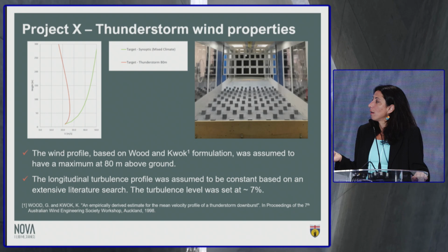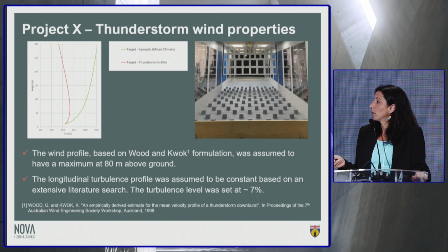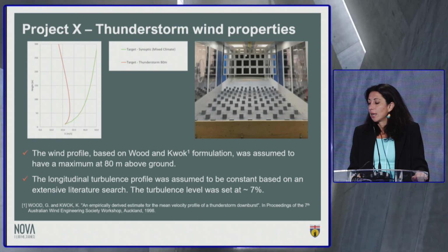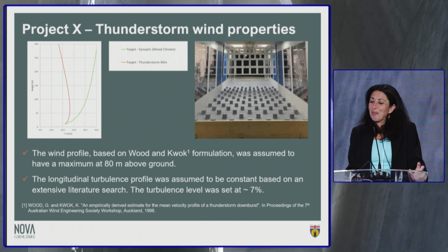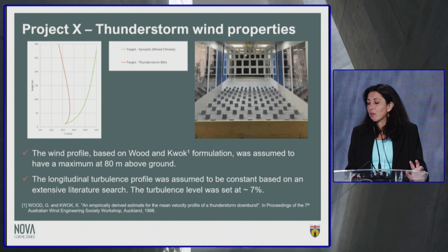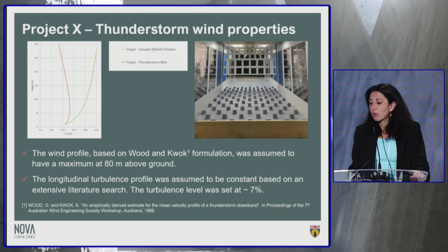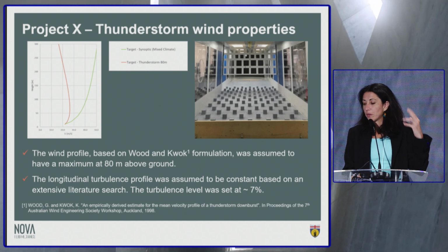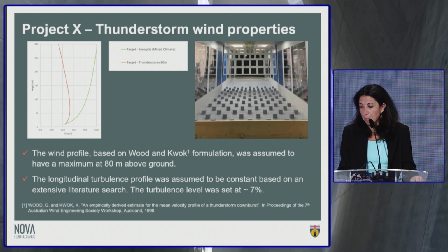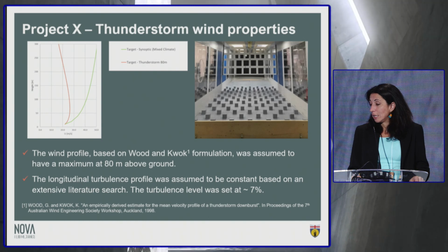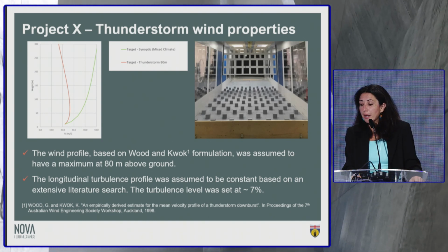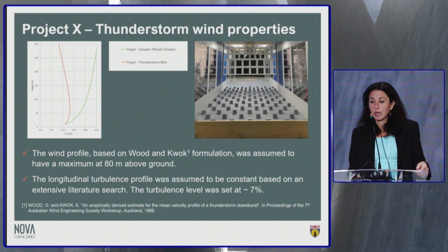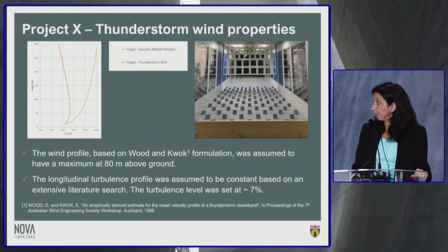Our favorite is the one from Kenny Kwok. Kwok and Wood provide a reference there, and it is, what is not our favorite, it's actually my favorite, because it's the simplest one, but it's also the most reliable based on full-scale measurements. This formula was written a long time ago. The paper was published in 1998, but if you compare this empirical formula with measurements that have been taken all over the world, it seems to be one of the best.